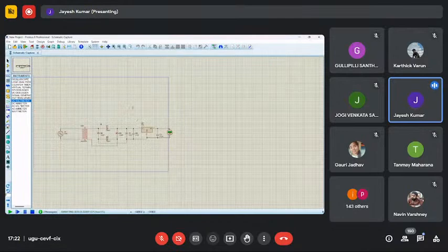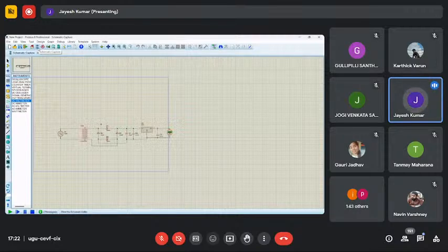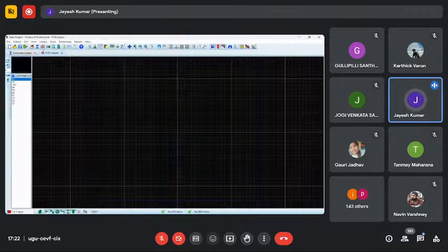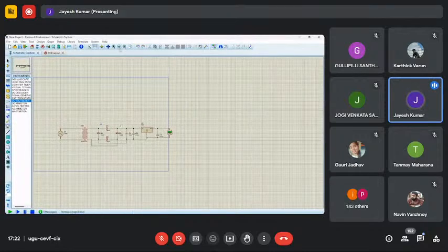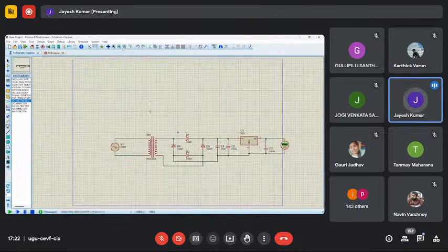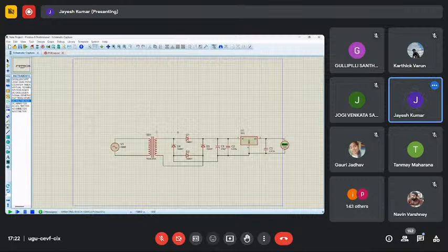Otherwise, here you can see the diode and capacitor symbols, and you can design the circuit from there. You can go to the nearby PCB layout design, so you can start with the PCB layout. You have to do the process in the schematic capture only, then you can import here. So you have to click on schematic capture and first do the packaging, so it can understand the architecturing structure and directly auto-port it to PCB layouts.